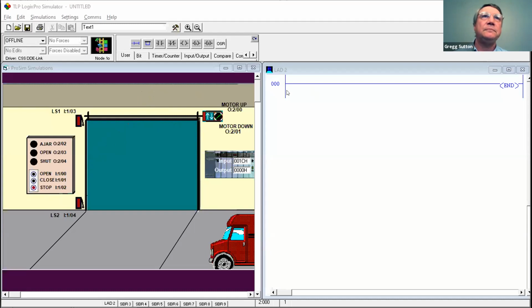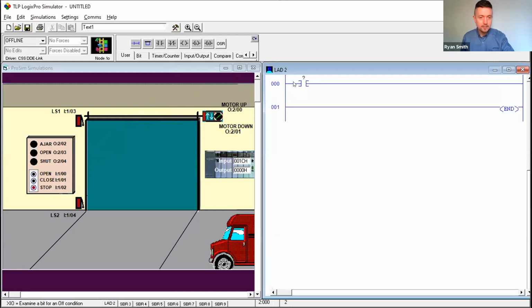Door will open. Okay, so no instruction is complete, as you said before, that it can input. So I'm going to grab an input. I'm going to drag it over to the programming ladder logic and plop it in. There we go. And then with each input, there should be an output. So I'm going to grab the output, drag it over right after the input. So now whatever the input does, the output will react to it.